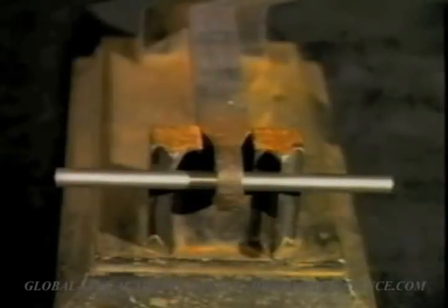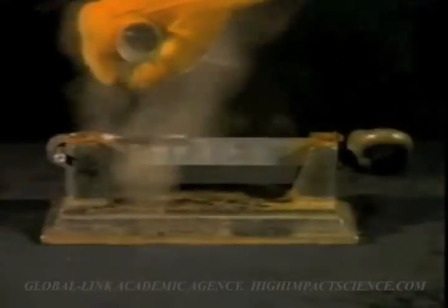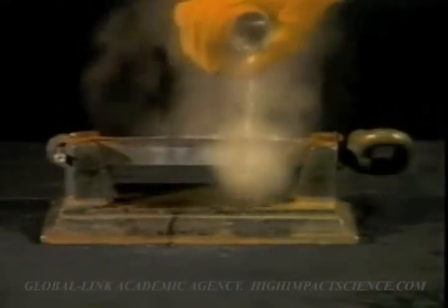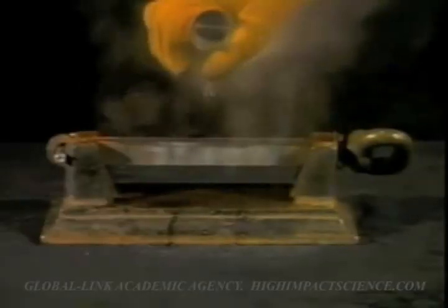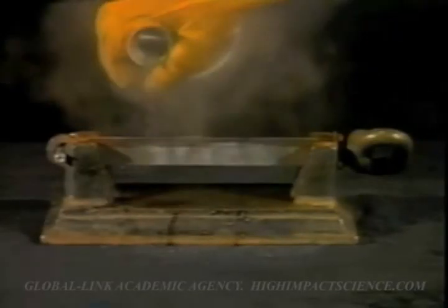As cold water is poured on the bar, it rapidly vaporizes, removing thermal energy from the bar. The resultant cooling of the bar reduces the energy level of the vibrating molecules, and the bar begins to contract. As the bar contracts, the rod becomes trapped between the iron bar, which is exerting a horizontal force in one direction, and the blocks of the fixture, which are exerting an equivalent force in the opposite direction.